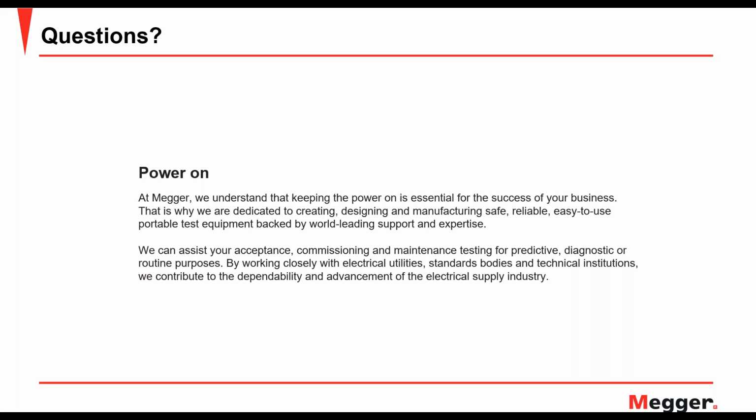So moving along, our next question is going to be from Volney. Will these tests also work for dry type transformers or only oil filled transformers? So it's a test in which you apply a signal and you measure the response. Any apparatus that has some inductive and capacitive effect will have a response. And yes, of course, it will apply for dry type transformers.